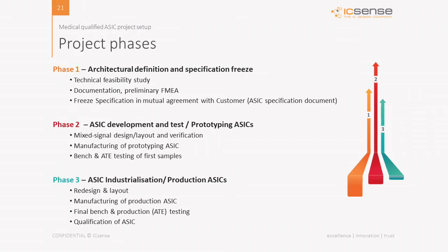Then within the second phase, when the design, the verifications and the simulations are finished, we start with the actual manufacturing of the prototyping ASICs. And when the chips come back, we will perform the first bench testing and start with the development of the production test if required by the customer. And based on these first silicon samples, the customer can actually start with the first field tests.